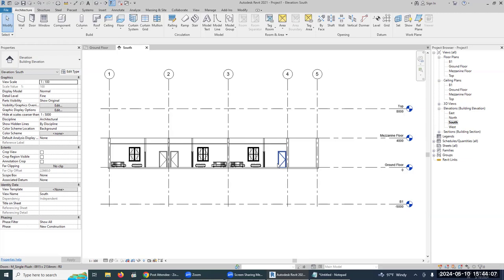I wanted to create a. Click it. Cancel this. But you only can do it. Now go to the elevations. Change as per this. Go to one of the south elevations. South. Update the sizes. What are the sizes I gave you? The 5,000, into what? The level to 4,000, huh? And that level to what? 8,000. Okay.